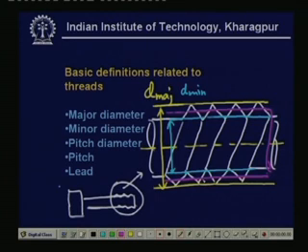That is the portion cut by the space between two threads, and that part of the cylinder, that is the axial distance between 2 points of the thread along this surface, these two are equal. So, this is x, that is also x. So, this is the special property of this surface, and this is known as pitch diameter. That is, the diameter of this is the pitch diameter.